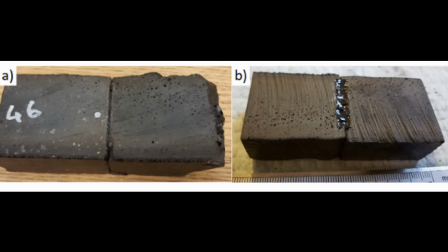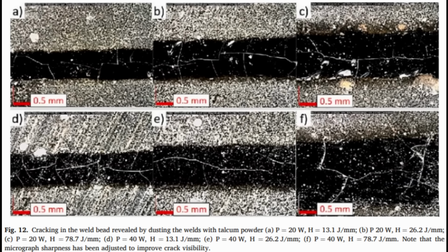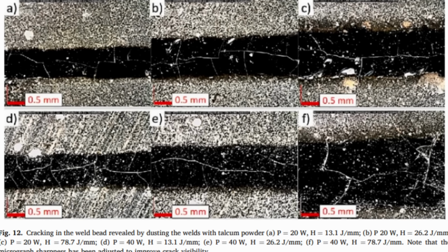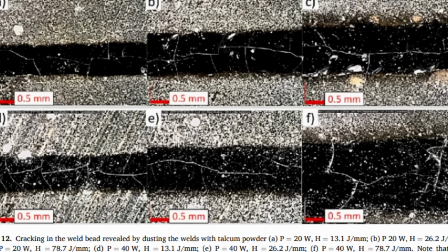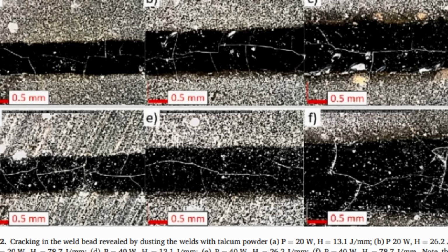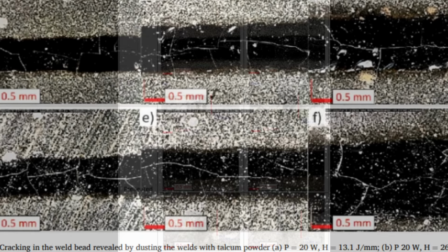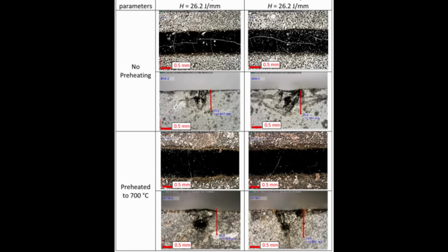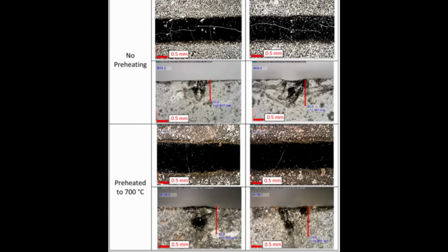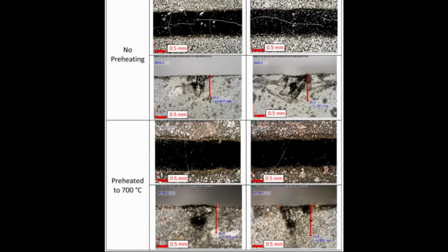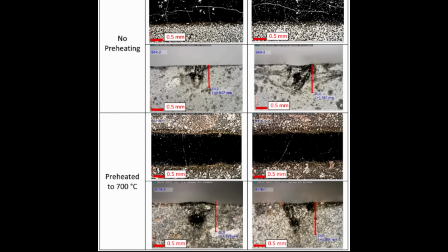The results were mixed. Basalt bricks can definitely be welded together, but unless you preheat the individual bricks to about 750 degrees Celsius, more than halfway to their melting point, then the weld is total crap, with micro cracks and pores causing it to have just 0.9 newtons a millimeter of strength, whereas if you heat the bricks up beforehand, you can get a solid weld with a strength of about 16.5 newtons a millimeter. Much better, but this preheat step would greatly complicate construction and increase costs.